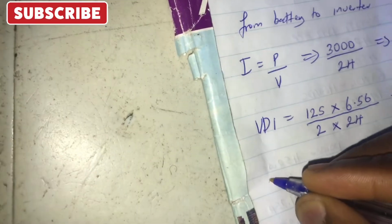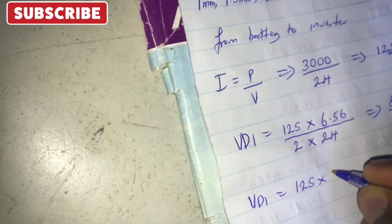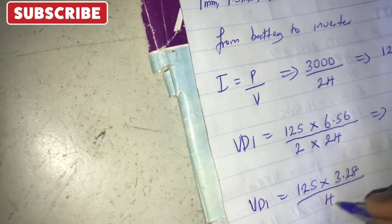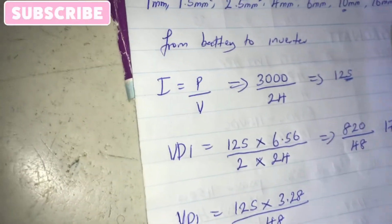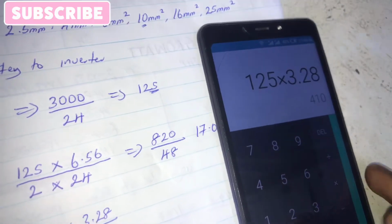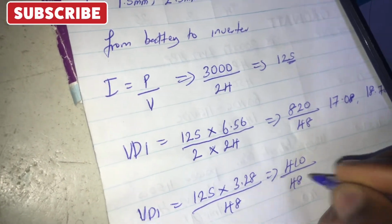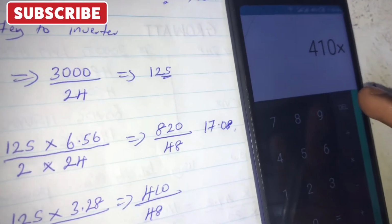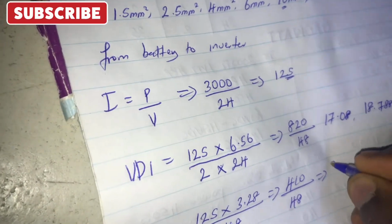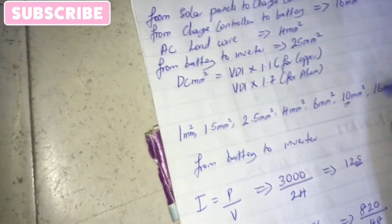Depending on the distance you are going with the wire, VDI will give us 125 multiplied by 3.28 over 48. Let's just go fast. So 125 multiplied by 3.28 will give us 410 over 48 volts. 410 divided by 48, giving us 8.5. So 8.5 here, the nearest is 10 mm.